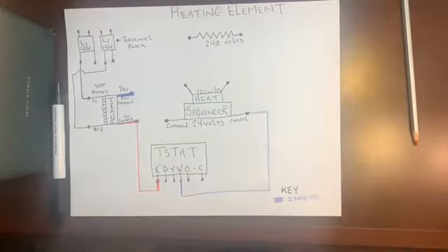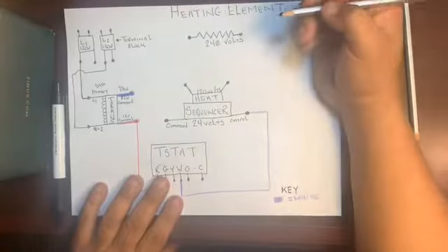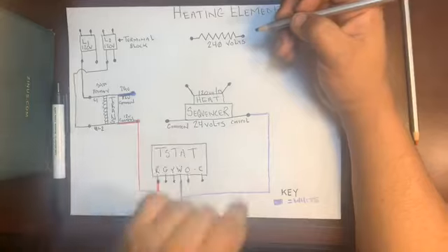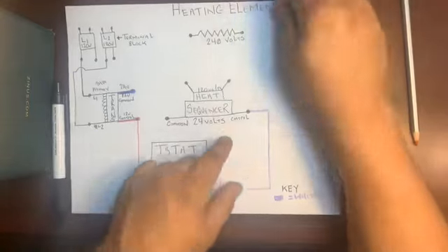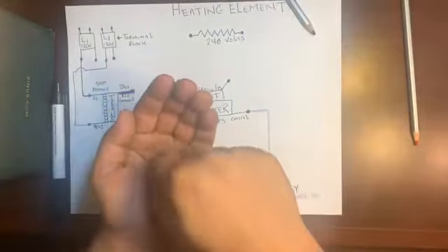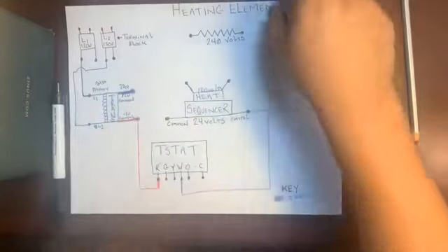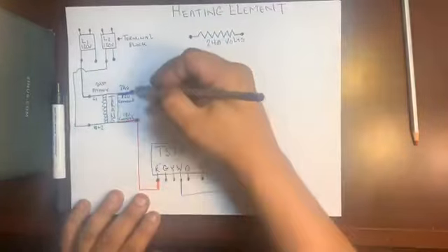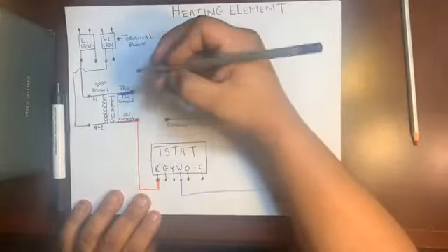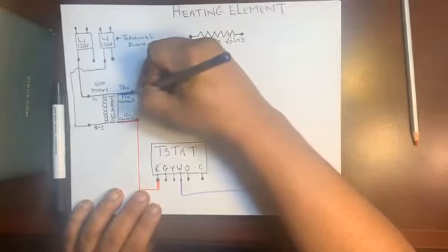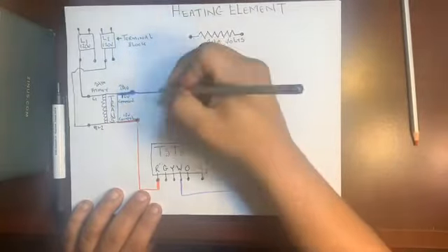Okay, so let's head on over to our common side. 12 volt common. What did we learn? Every relay has two hands of low voltage, common and control. Two hands. I don't even gotta say it. Put the common in my hand. Common right here, common right here. On the secondary side of the transformer, we're gonna come over and just drop right on down.